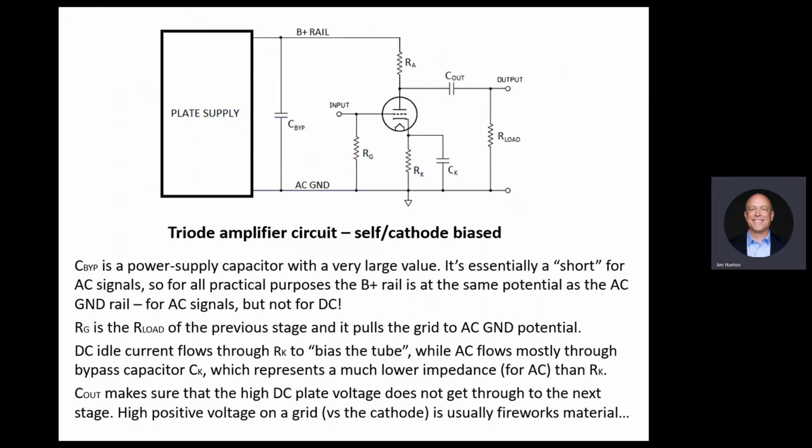And if anybody will tell you you can put an electrolytic and not worry about it, don't. You need to bypass this electrolytic if you want to get decent results, because the electrolytic will be fine for DC, not for AC. And you need the AC behavior of the circuit.